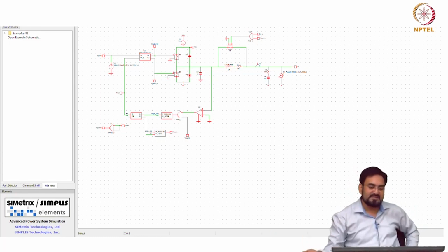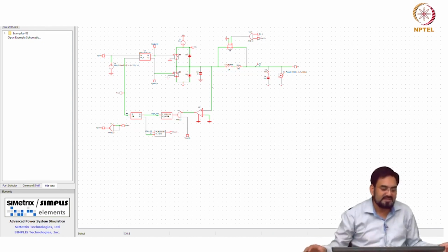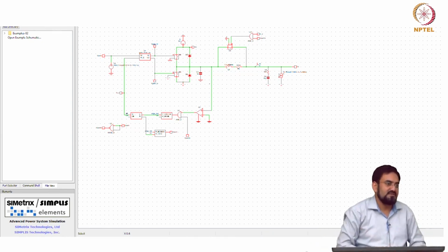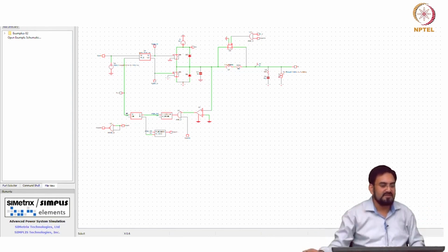And that is what happens. The inductor has stored the current here, and even though you turn off this switch, that current has to be dissipated somewhere, and it dissipates in this parasitic cap and causes the resonance. And that is why this voltage goes high, and when this voltage goes high, the voltage across the inductor goes positive and it will try to get the reverse current.